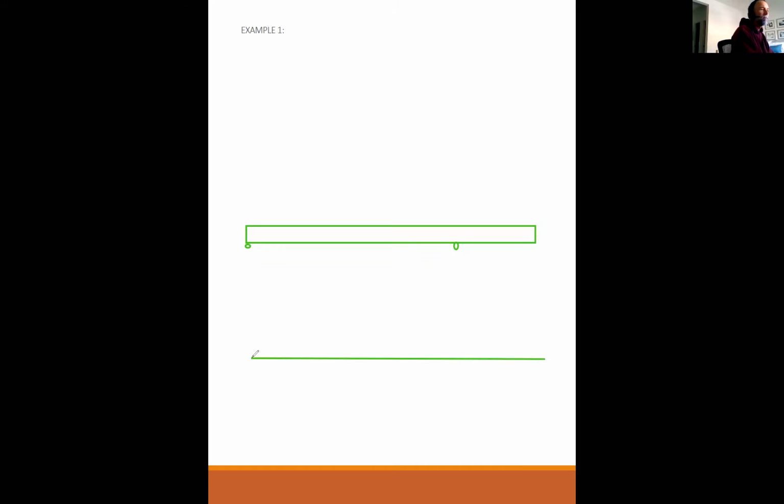But the moment diagram goes like that and like that. Okay, something like that. And then, if I'm understanding the question correctly, in the positive moment, you need rebar on the bottom of the beam, and in the negative moment, you need rebar in the top of the beam.